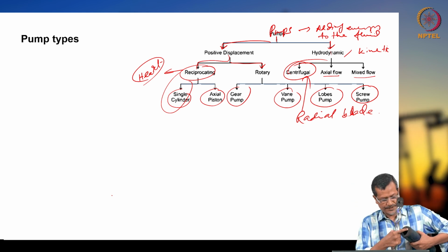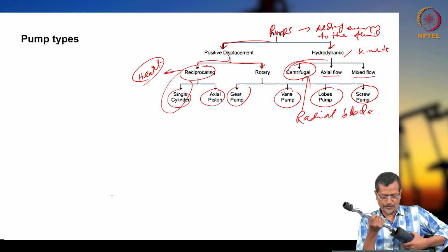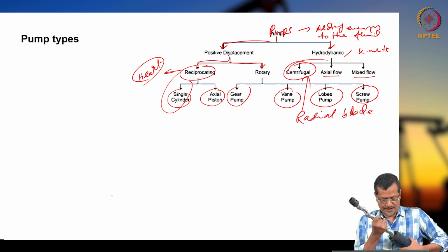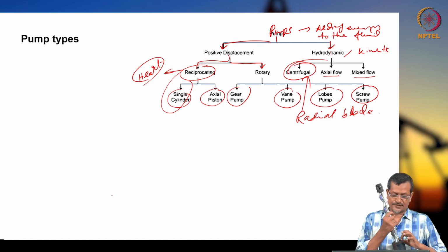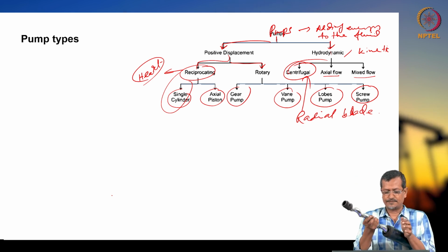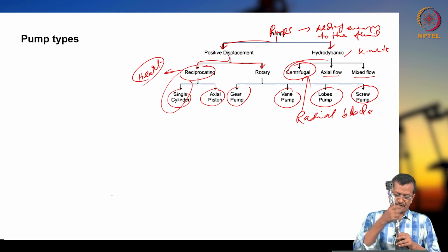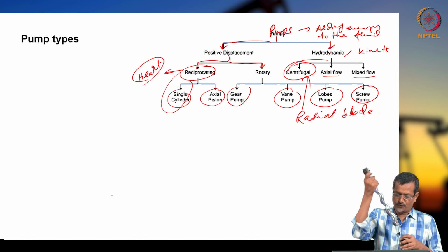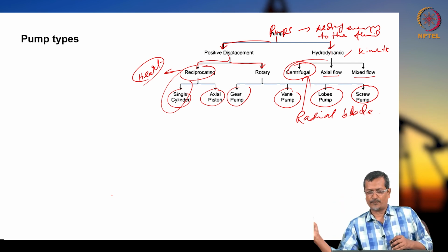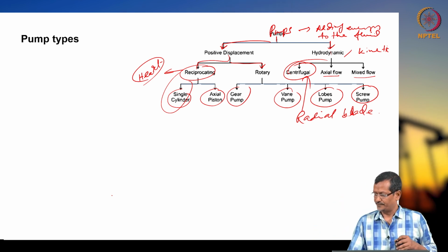If you see this stator, the stator is having one hole. So this rotor will be going inside this one, okay. And inside there is an elastomer coating here. This is solid metal, and inside this one is the elastomer coating. So when the rotor is rotating inside continuously, fluid will be delivered from one point to another point, okay.